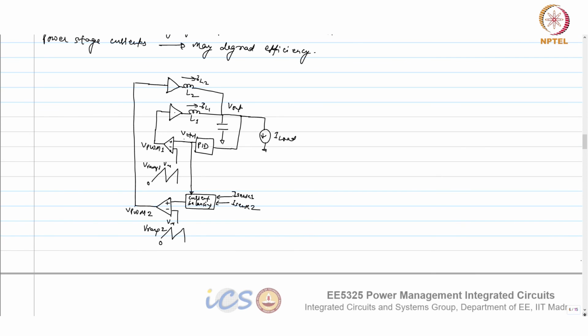So, let's say I have 5 delay cells in the ring. So it's a 5 phase. I can tap 5 phases from there, but ensuring each delay cell is exactly the same or matched is very difficult. So the phase to phase mismatch may be there. That may cause a difference in the duty cycle, multi-phase.